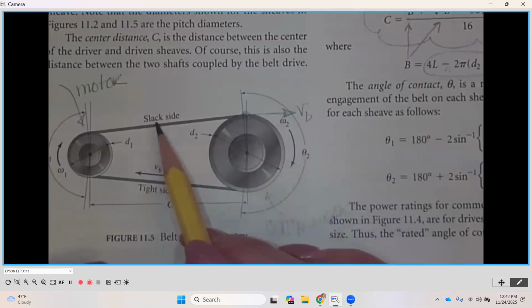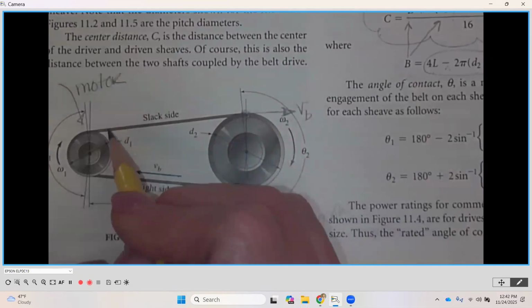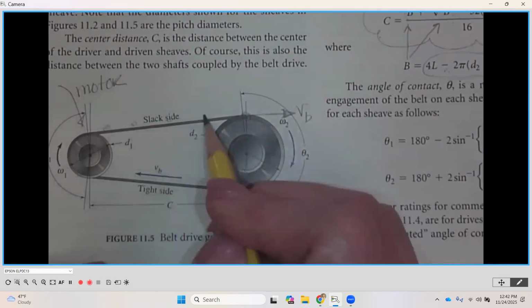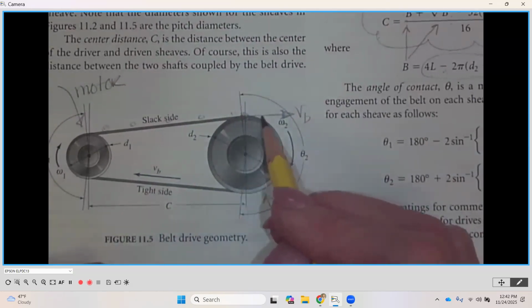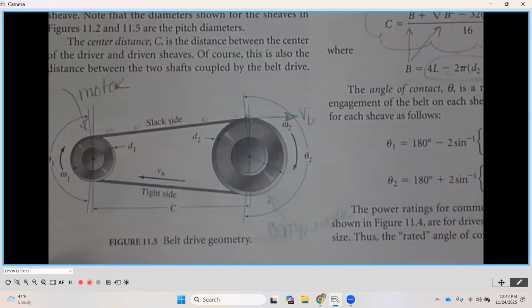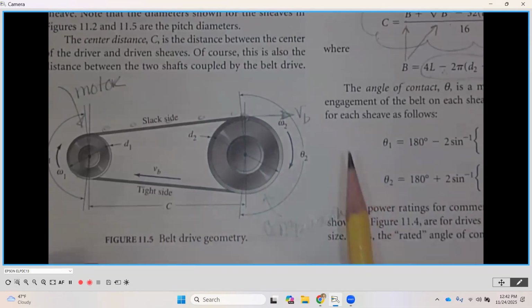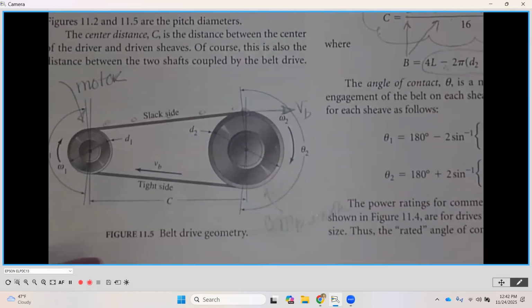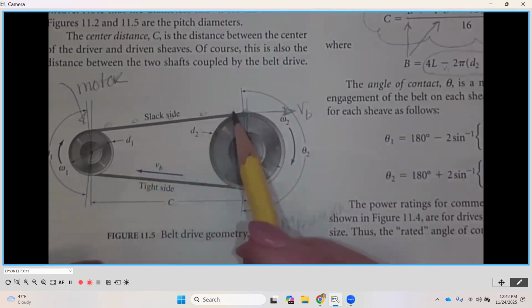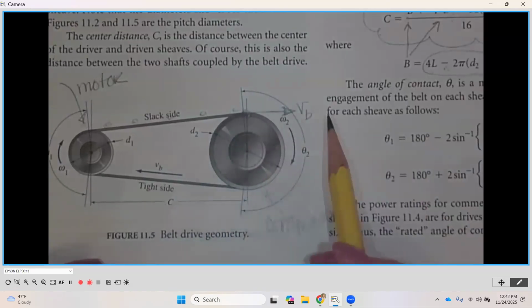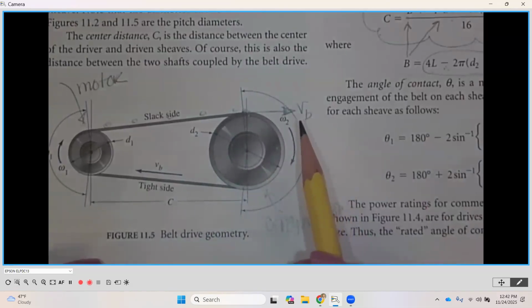That is representing how fast that belt is going along. So if there's a pebble on the outside here, when it gets here, it's going to fall off, but it's going to continue at a straight line velocity. That's what we're going to call the belt speed, because as it's here, it's going along with the belt, but then it can't make the corner. It's going to continue going. Does that make sense, everybody?